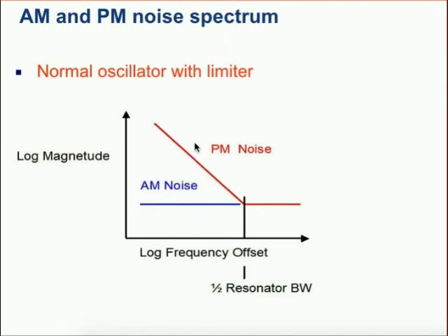First of all, it's important to understand that a resonator can be modulated at a much higher frequency than its bandwidth. The bandwidth associated with the Q of a resonator, or even if we have a positive feedback system increasing the Q, that bandwidth doesn't limit the rate at which we can modulate it.